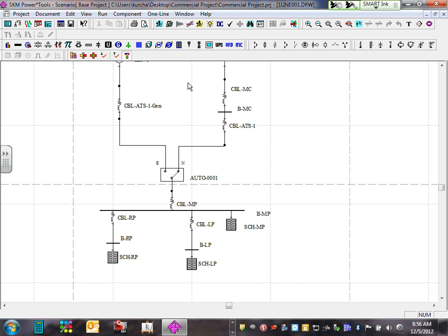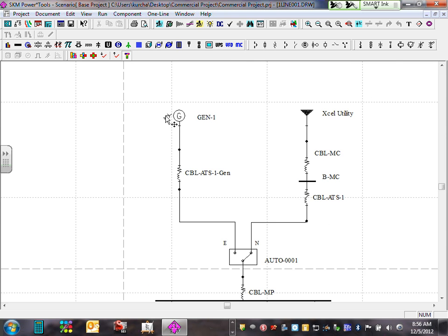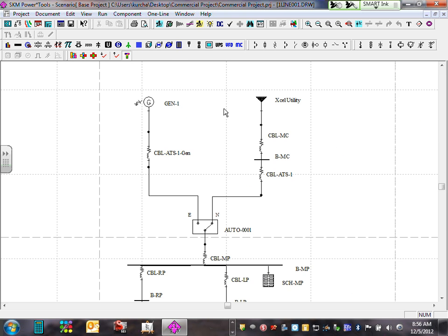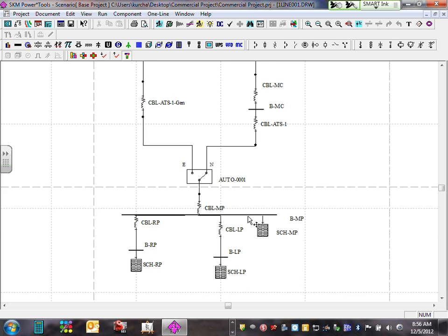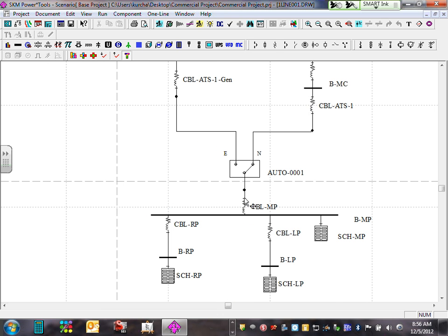Okay, as long as we're on it, let's go talk about the generator before we move into the cables. Well, you know what? We'll do the generator next. Let's just finish the cables since we're on the cables. Now, this cable here, guys, is going from the ATS into the panel. What's the difference between this cable? Thank you, EMT. So I can't use this cable.